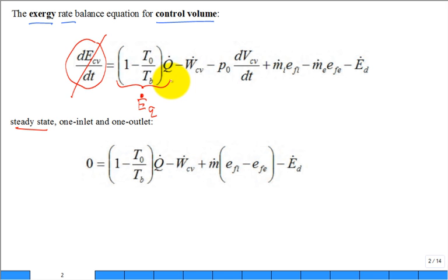And then we looked at this multiplier in parentheses. What did that look like? Carnot efficiency. 1 minus T low over T high. So it's some percentage. If I'm transferring 1 kilowatt of heat, maybe only 0.3 of it is the rate at which Exergy is transferred with that heat transfer.